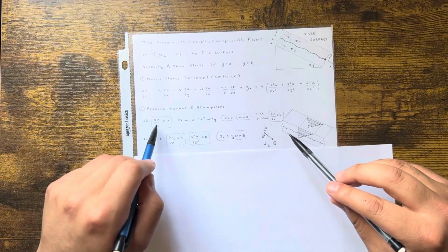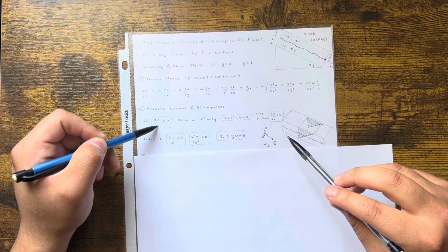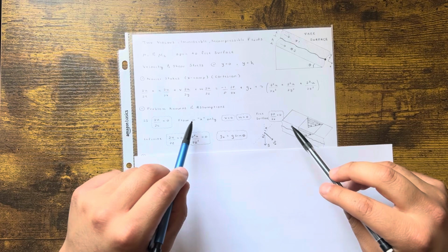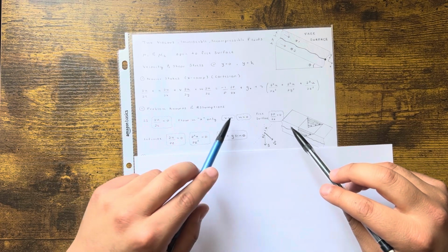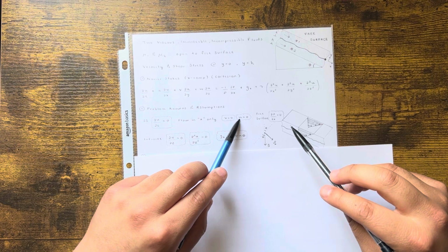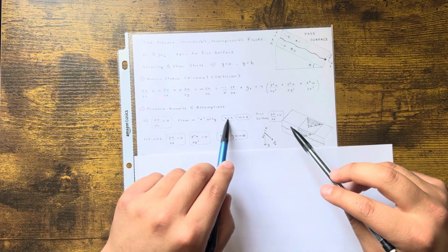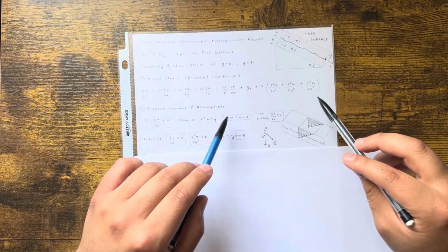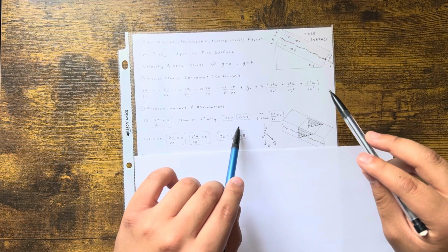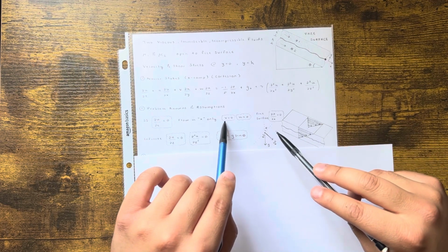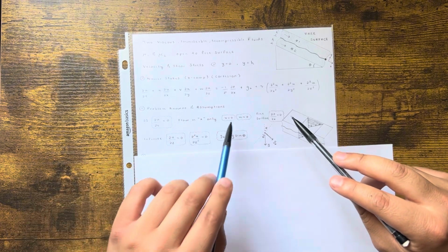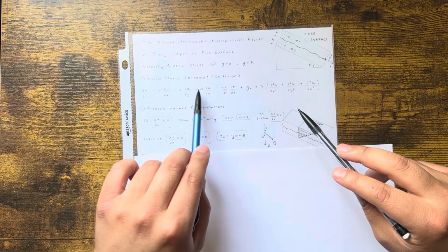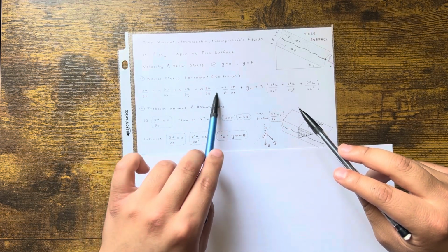In this case, it's steady state, so this term goes away. Anything related to time goes away. In this case, it's just this one, so we're good. There's flow only in the x direction. So you have the y flow, which is v, and w, which is z. Y and z, they're both 0. We only have flow in the x direction, so just because of that, these two are 0. Anytime you take a partial of v with respect to anything, it's going to be 0, because the derivative of 0 is 0. So this term cancels out, that v and that w. Just like that, we're left with this term on this side of the equation.